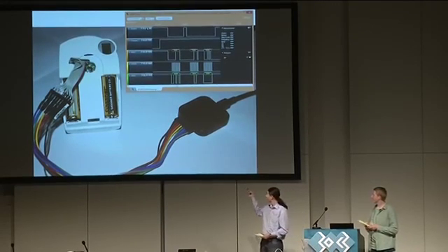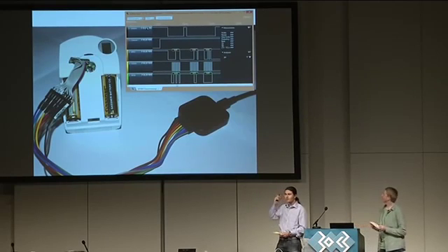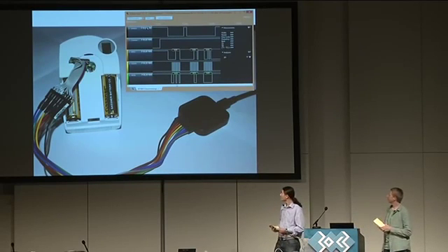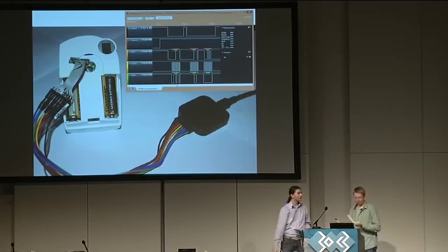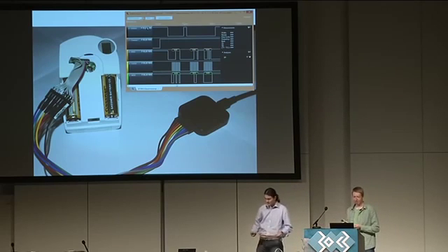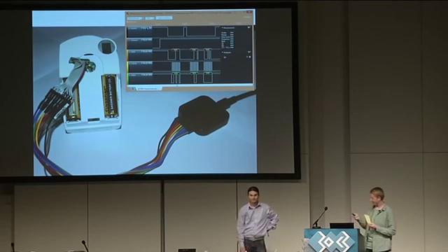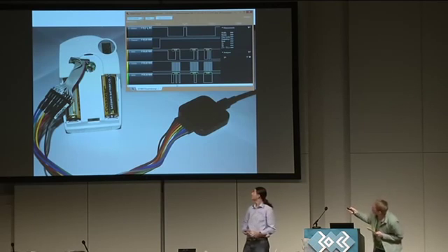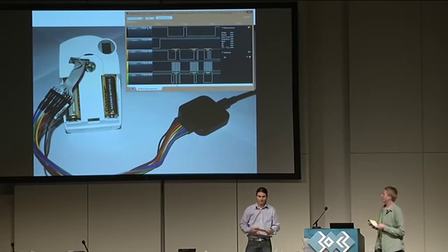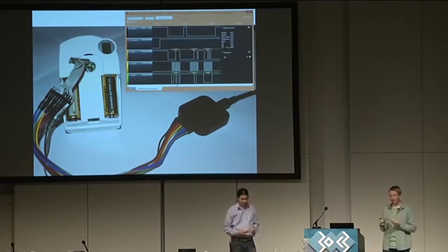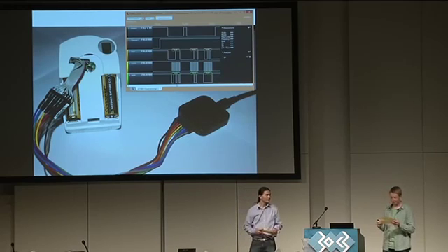So we sniffed the traffic on this communication interface with a logic analyzer and soon understood how the device works, and we could soon emulate this valve drive. Actually, this valve drive, as you can see here, is already running our own firmware, which we later did not develop anymore because it was not necessary.